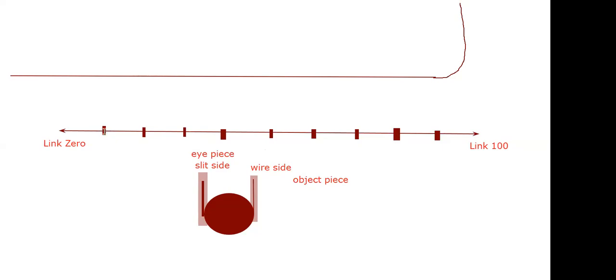So you will stand there, you will ask your friend to take a ranging rod and place the ranging rod somewhere here, and you will use this magnetic compass. Keep it on your palm, absolutely straight. And from the eyepiece, you will check the position of the ranging rod. The ranging rod should be exactly behind the wire. This is the ranging rod and it should be exactly in front of.